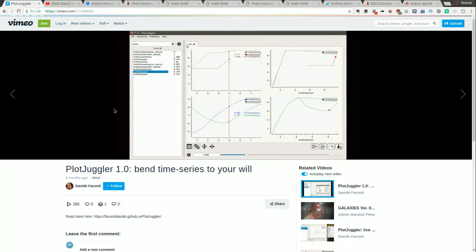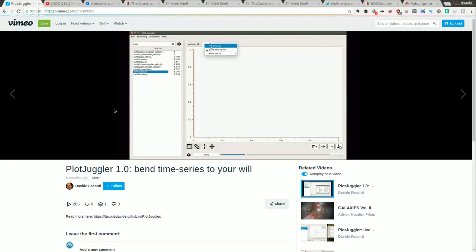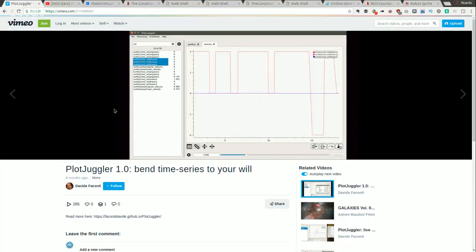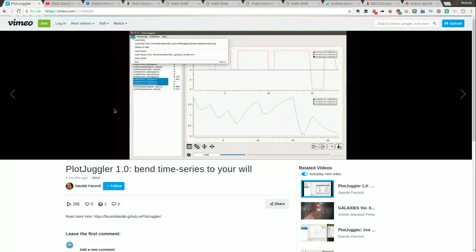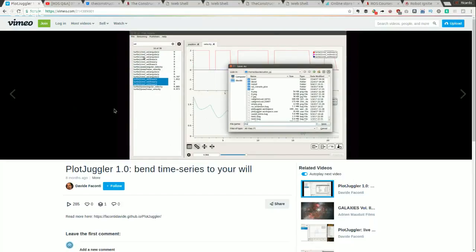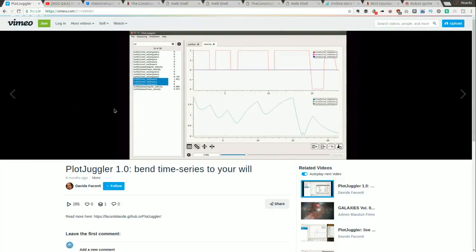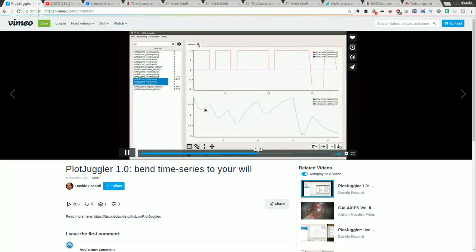So this is very useful in case you need to check where your robot is failing, and why it's failing. When I detect this sensor value, why is the robot not moving forward, why is it not rotating, etc. So you can check at which point. This is a very valuable tool because it allows us to visualize all the values that the robot is generating at a given time. So I highly recommend it. I will do a session one day with further details about how to use it, to take more advantage of this tool. So just give it a try and let me know what you think in the notes of the program.